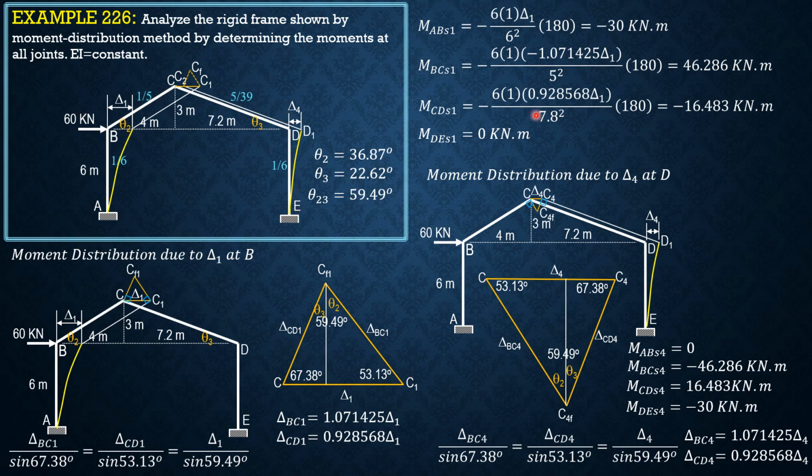The moment due to side sway in the second phase would be these values, and the moment due to delta 4 side sway would be this. So this will be in terms of R2. Then we need equations of statics to set up equations involving R1 and R2.